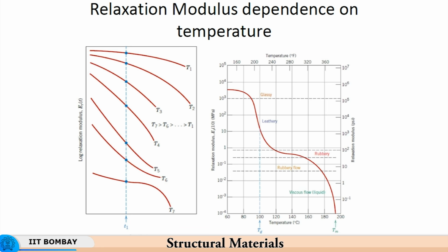So you have molten polymer which is viscous. There are polymeric chains floating there, and these chains are generally randomly arranged with respect to each other. When you do an injection molding type of process, when you extrude the material in a liquid form, or you inject the molten polymer, these randomly oriented chains tend to get aligned.